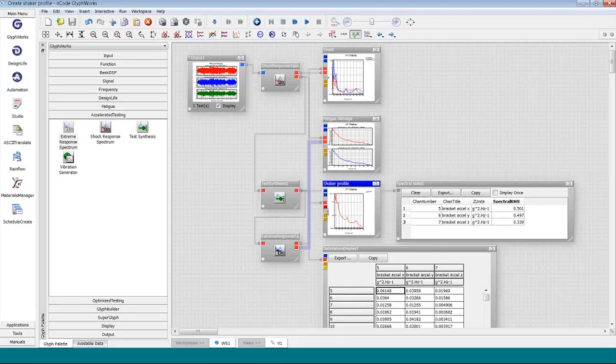How do we take measured vibration data and convert that into a shaker profile that can be reasonable? The shaker profile I've been looking at here was a PSD random. We can certainly extend this into PSD random plus a sine tone or a sine sweep. A sine sweep on random is a popular thing these days. We have techniques for dealing with that, but for time I'm going to omit that.